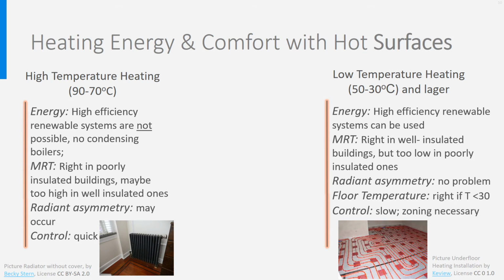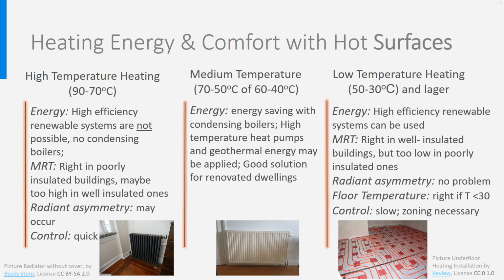Well, and of course, between high and low temperature systems, everything in between is possible. In general, medium temperature is suitable in thermally renovated dwellings that do not achieve new built insulation levels. Note that the pictures in this slide relate to water systems. The findings on comfort are exactly the same for electrical radiators, but the use of electricity for direct heating is not recommended as it is very inefficient, as you can learn in the MOOC Energy Supply for Buildings.